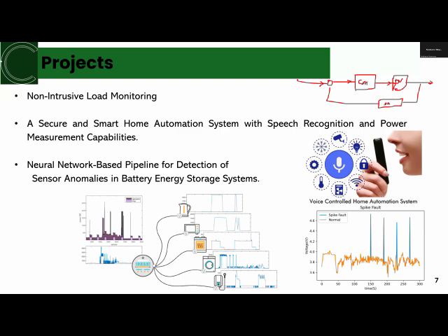Now, what we have done here is add a part, an AI model, after the sensor, which is going to monitor the sensor performance. If the sensor performance is correct, it will transfer the data to the control system. If it detects the sensor is not performing according to an accurate scale, it will inform the controller to stop the operation because the sensor feedback is completely wrong. In that case, we can avoid unnecessary accidents.